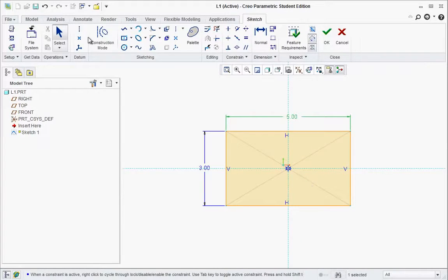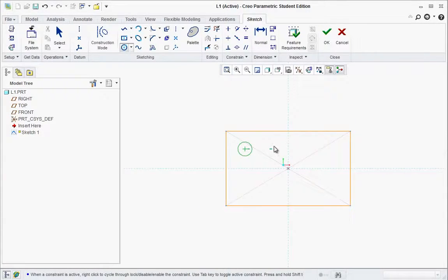Alright, now that we have it centered, we could also draw in some center points, or some circles, because there's some bosses that are going to go in here. So you could click on one side here, and then over here you could align to it, drag another one out, and the T equals that it's tangent, so you want to stay away from tangent, but you do want R and R. That means it's making those 2 circles equal. And again, you could align yourself with the R, and then here you could align yourself to both, get the R again, so they're all equal sizes.